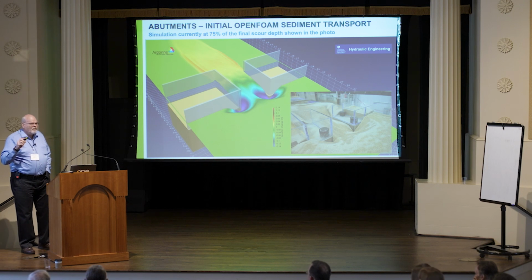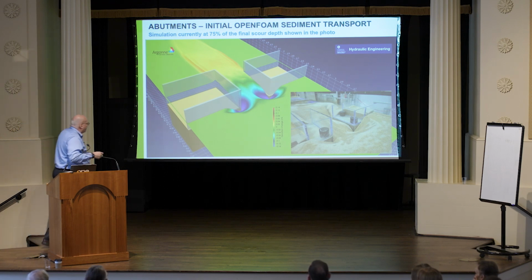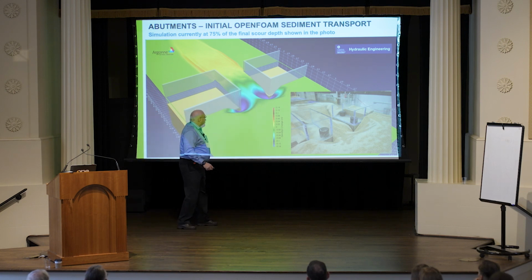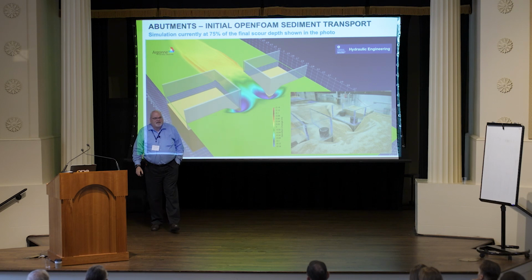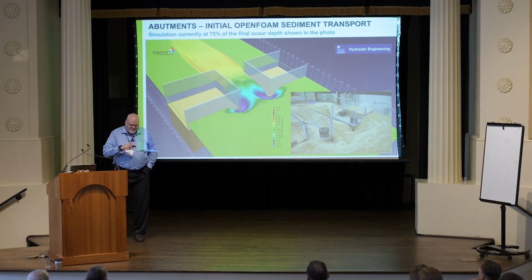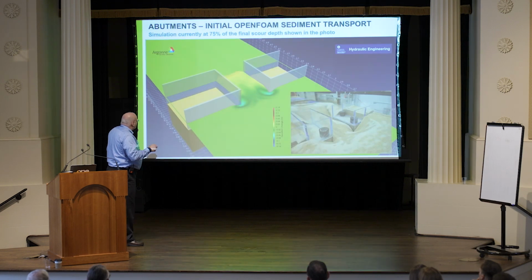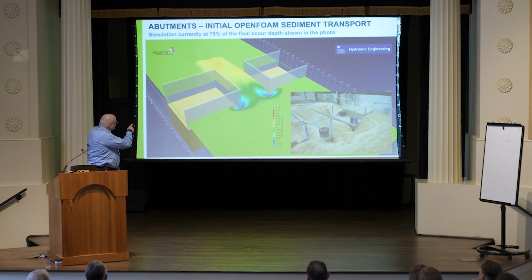Now, mostly this is important for two things. One, the far away formation where the water flow slows down on the riverbed. That's where mountains would form. The other thing where we have to get it right, and that's why we still have to look into this, right in the center of our bridge opening, there might be material deposited. I mean, let me try to go back. I think this is my last slide anyway, so let me start it over again. So you see that the material is piled up initially between the piers. So everything yellow is above original ground.